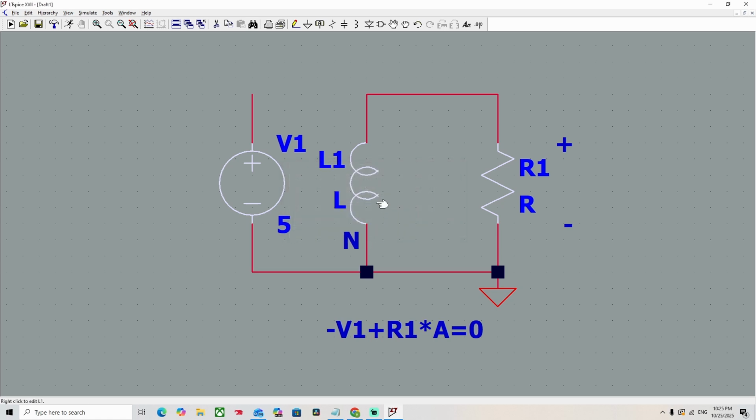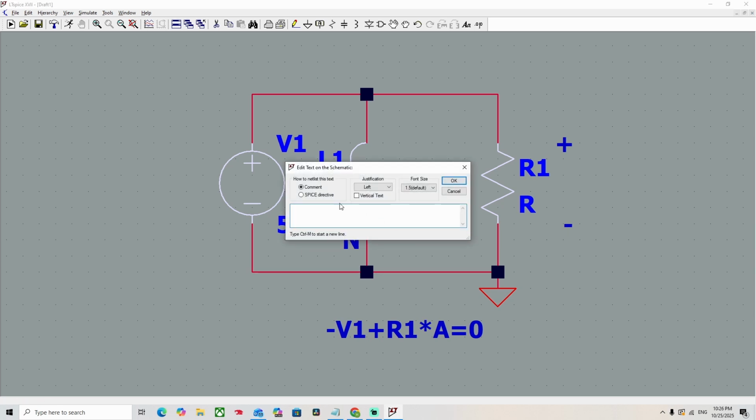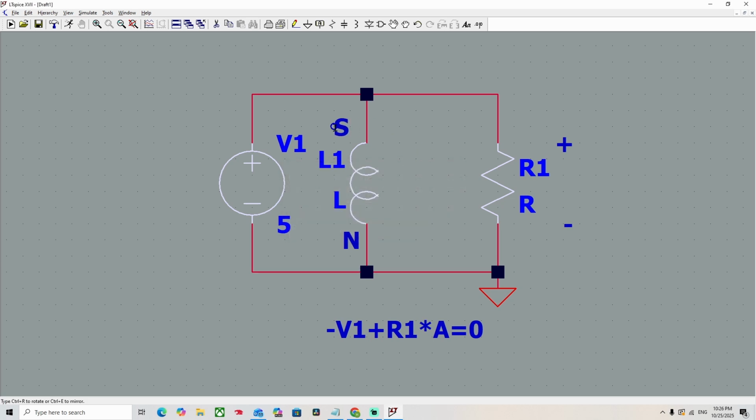The North Pole would be down here in this instance because of the way the current is flowing. Sorry, let me just draw back the wire here. So current is flowing down counterclockwise, going this way. The North Pole would form at the lower part of the inductor, and the South Pole would form at the upper part of the inductor.